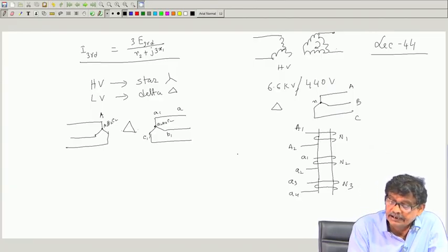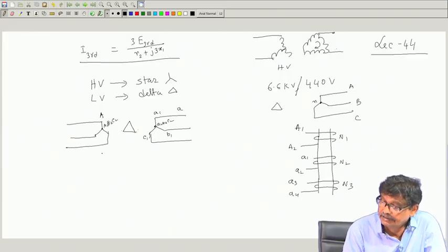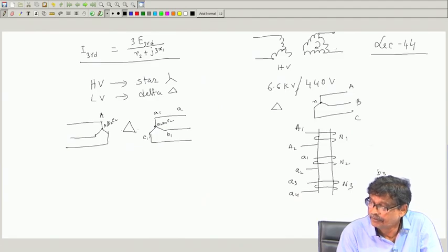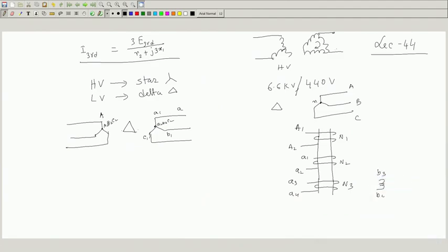And this one I have connected in delta, this a3 a4, similarly you will have b3 b4, I think you are understanding what I am telling, and you will have c3 c4 like the other two limbs, and these I will connect in delta, got the point. So, you connect them in delta and three terminals will come out.